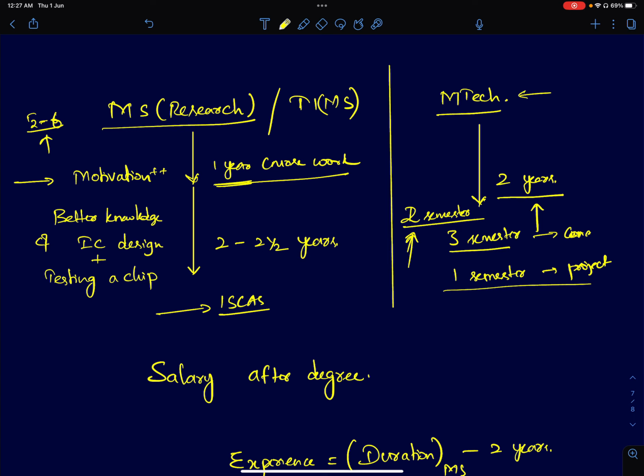Now, once the idea works, you know that the idea is working, then you start schematic designs. At architecture level, it's working. You start your schematic designs. And that schematic design, layout, taping out, that usually takes at least 1 year. This is a minimum duration. Schematic to layout, layout to tape out, then sending it off for silicon.